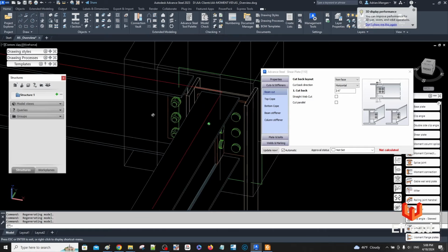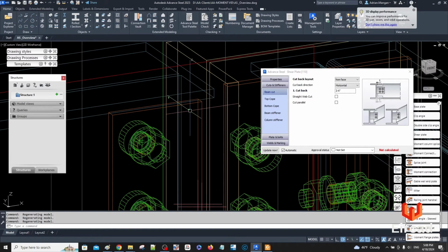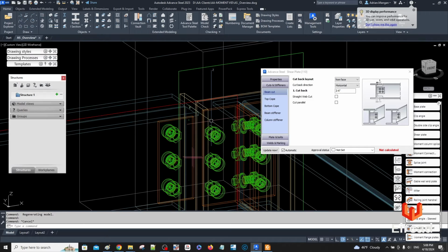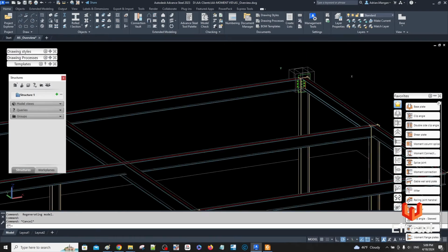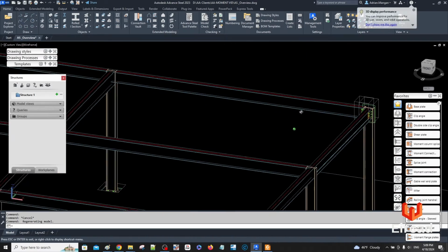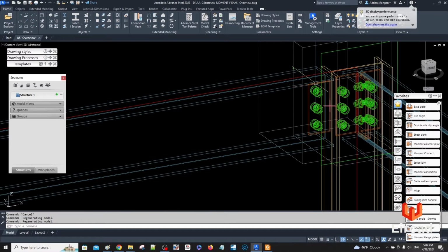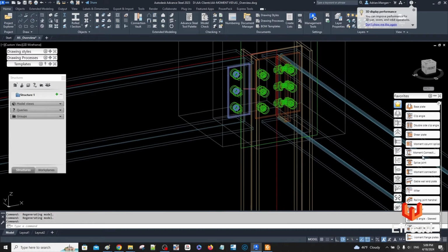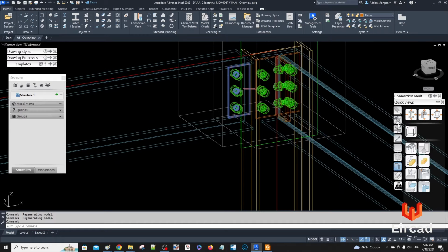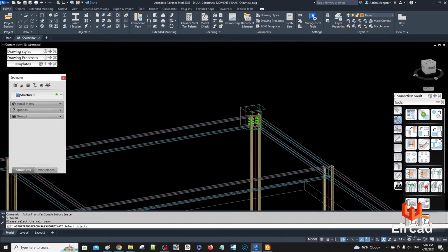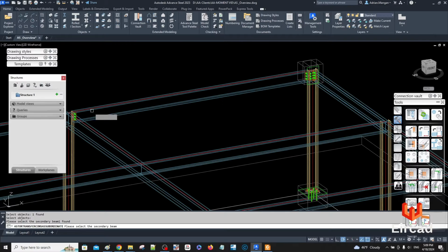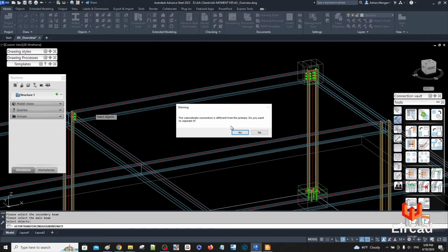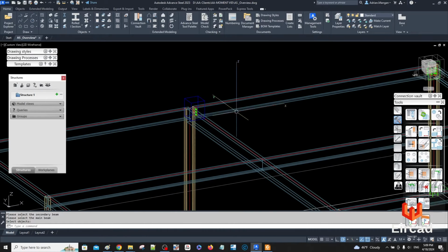So now we have that connection on the beam. It's also got the punch mark, so you know which side of the beam it goes on, and it will do this automatically on your plasma machine. So right now, that looks good. So now, we could do the same thing. We can copy this connection using this parent-child relationship. If we do that, it's different, right? Because it's put it on another side of it. So I'm going to say no, we'll keep them the same.